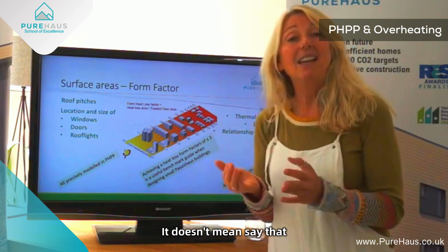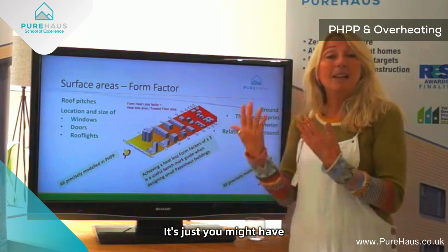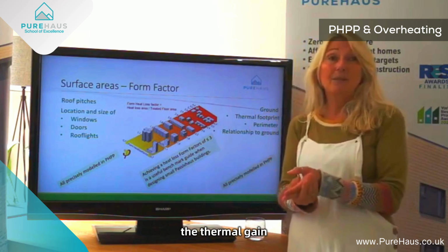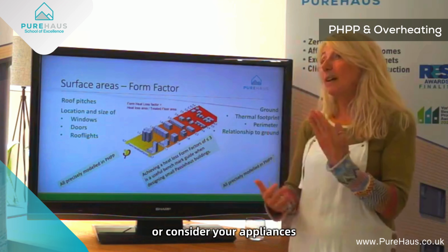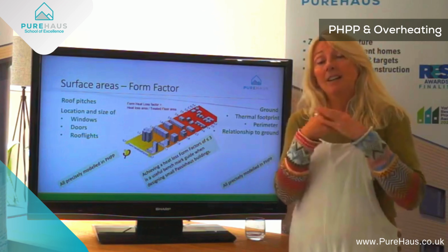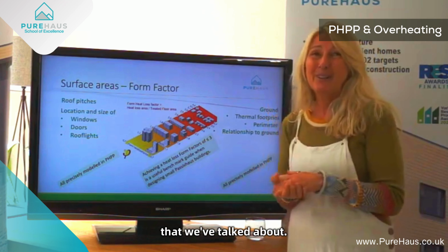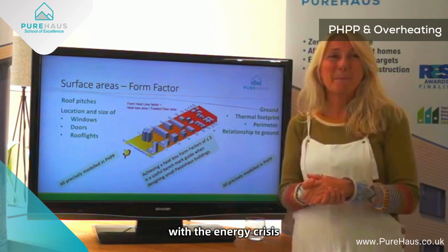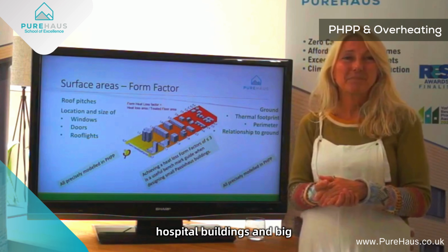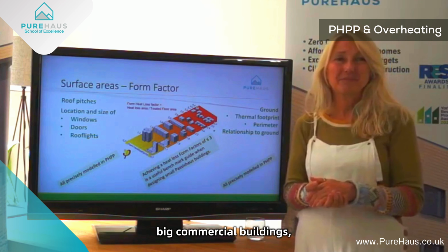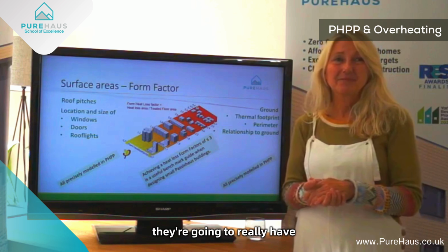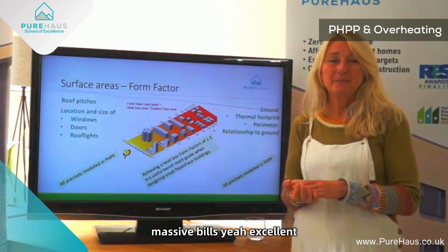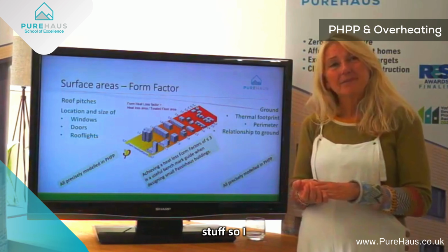It doesn't mean that you can't do it. It's just you might have to up your U values, or you might have to really work the solar thermal gain, or consider your appliances to be more efficient, or all those other aspects that we've talked about. Particularly at the moment with the energy crisis, the large hospital buildings and big commercial buildings are going to have quite a poor form factor, and as a result, they're going to have massive bills.